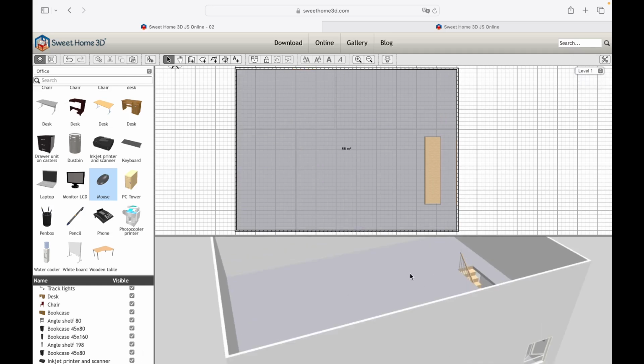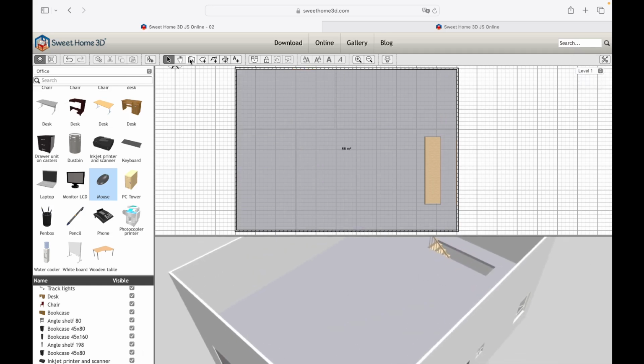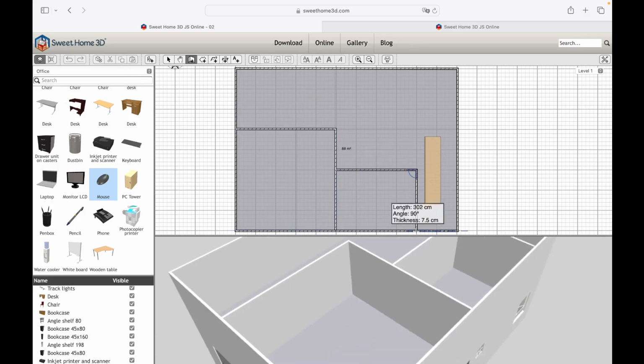With the Create Walls tool, we proceed with the subdivision of the spaces. We build a room measuring 5 meters by 5, one measuring 3 meters by 4, and the last one measuring 3 meters by 6. In this way, we created a large entrance hall, 2 bedrooms, and a second bathroom.